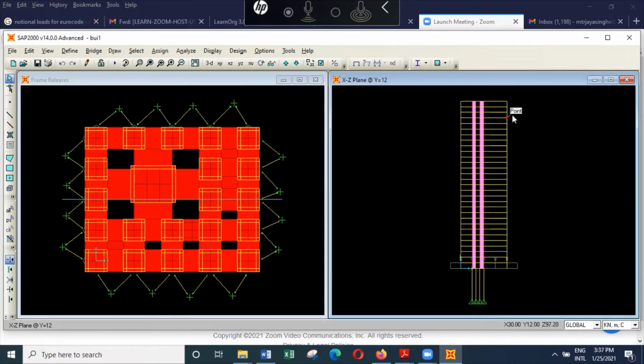And I will consider that the leeward side coefficient is minus 0.5, and the windward side coefficient is 0.8. Last time in the example you saw those values are 0.8, and the leeward side can be a maximum of 0.5. So I consider the load as 1 kilonewton per meter squared. In your case, if you want, you can actually calculate the actual value, but I'll take 1 kilonewton per meter squared.